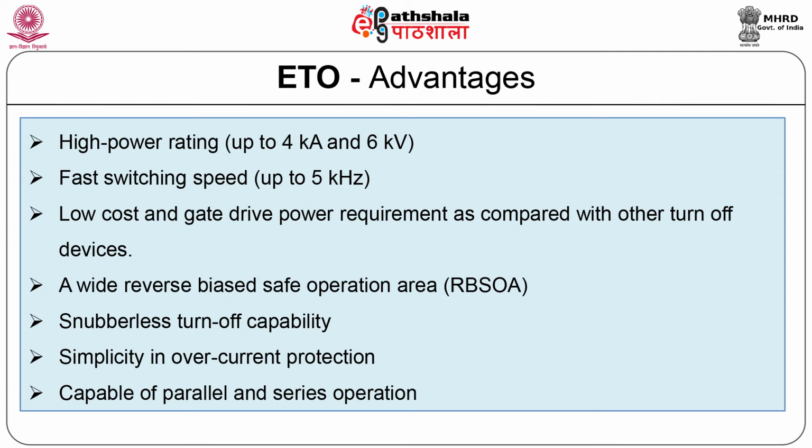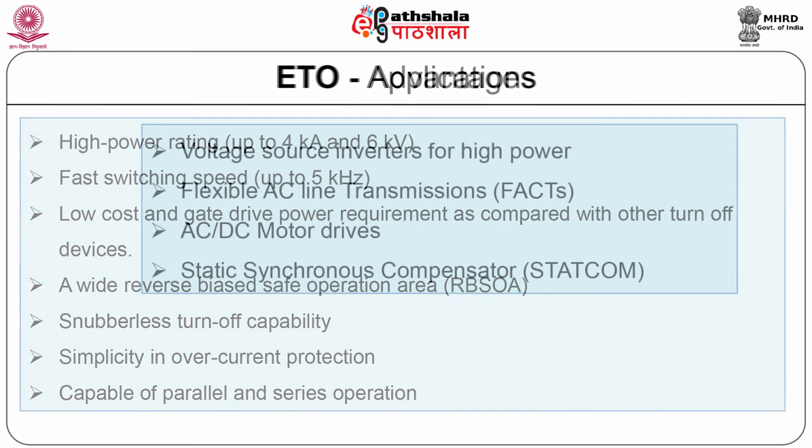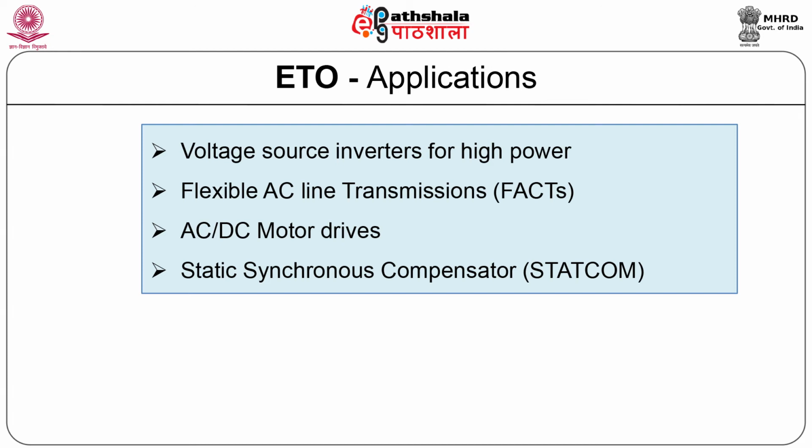Most important advantage of ETO is that it has inbuilt current sensing capacity, so it simplifies the overcurrent protection. It is capable of parallel and series operation. So, these ETOs can be used in VSIs, PACs, AC/DC motor drives and static synchronous compensators, that is STATCOM.